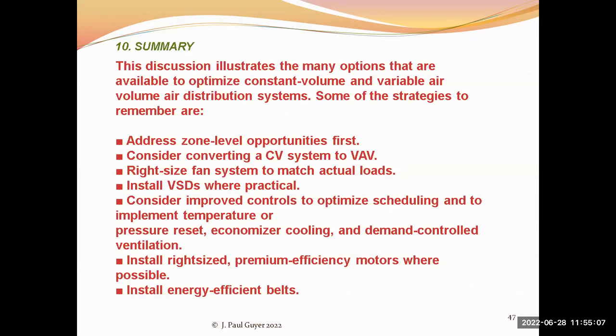Install the variable speed drives wherever practical, particularly if you're going to convert from a constant volume to a VAV system. Variable speed drives are a very important option to consider. Consider improvements to these controls, and then right sizing the motors, and use premium efficiency motors where possible, and install energy efficient belts.